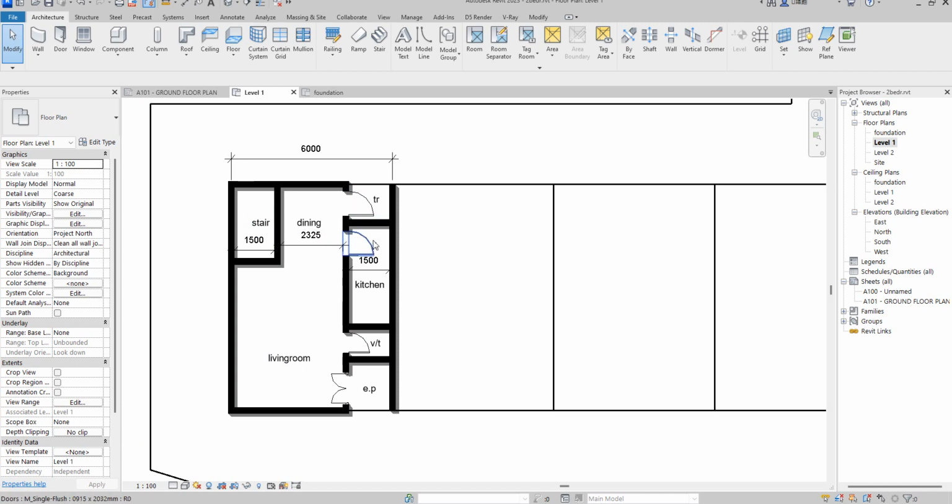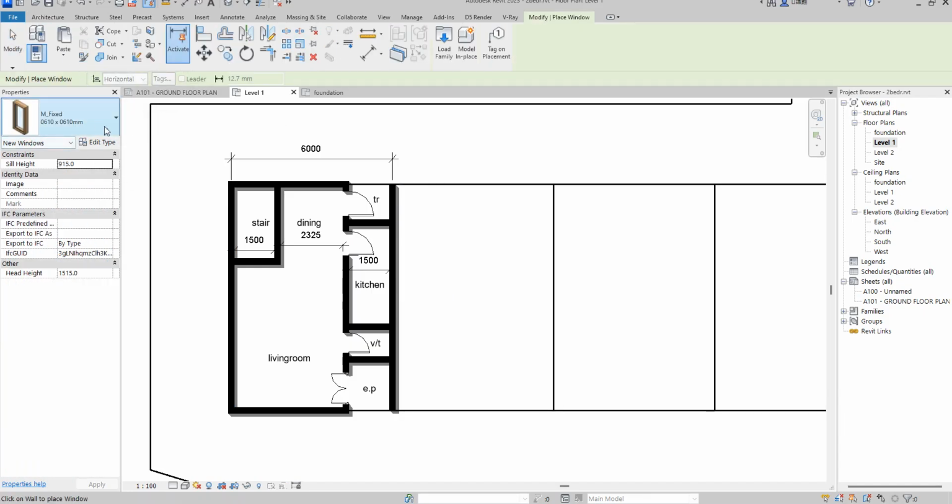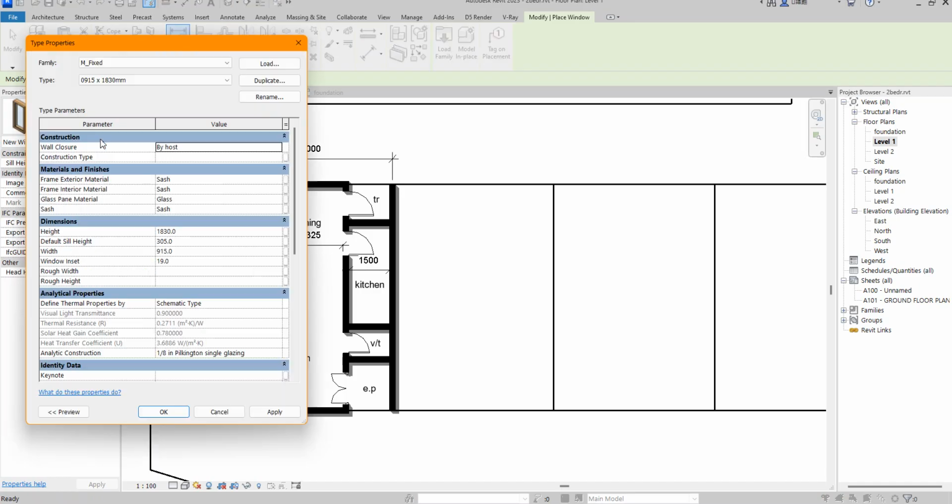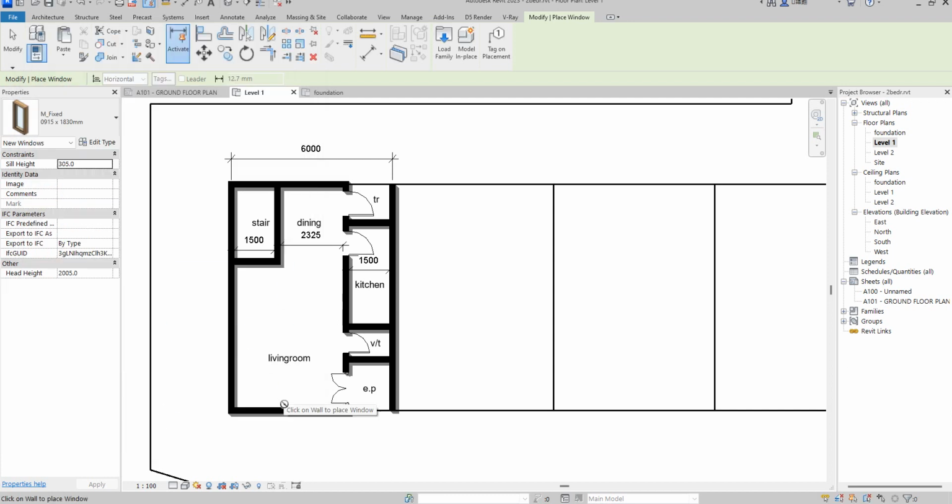So we were able to bring doors into this one. So let's quickly insert some windows. The kind of window I want to use is just a long window, precisely, nothing more. So I'm going to use this casement fix. Make sure the height is 1700. Then I'm going to use the width to be 800. I'm not going to use 900. So 800. So what I do is that I change this one to 2100.